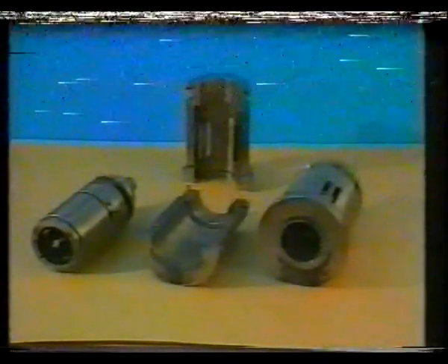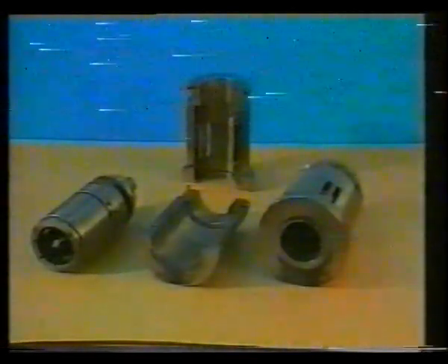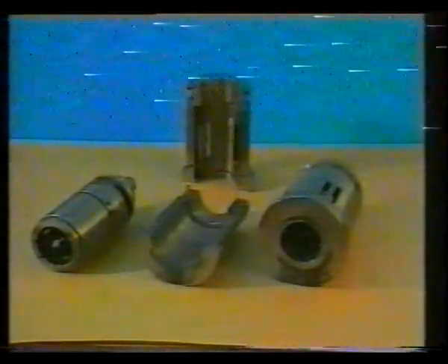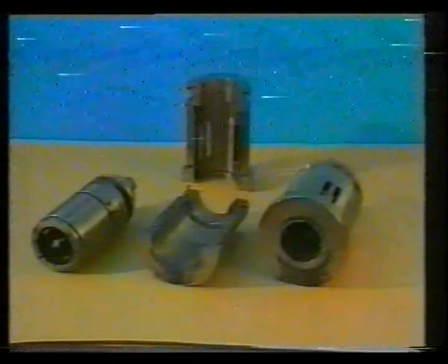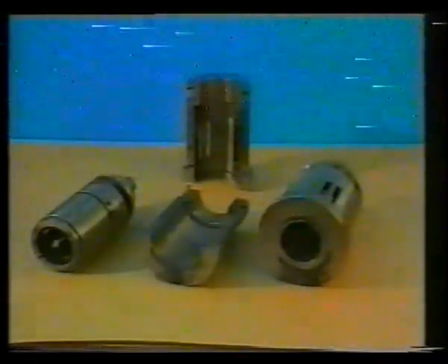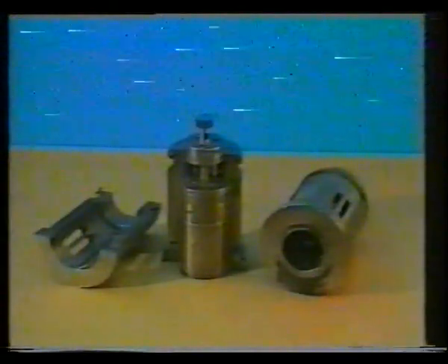The die design is such that, for instance, when there are die inserts in the movable die half, only the inner bushings have to be changed. The exchangeable components can already be prepared while production is still going on. In other words, in parallel to the production process.